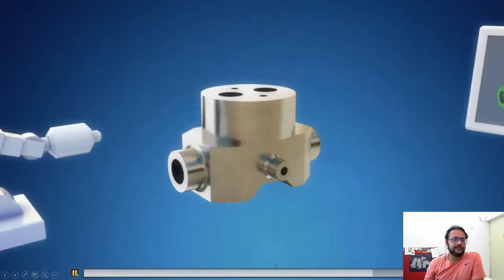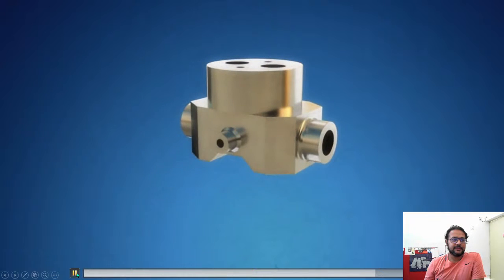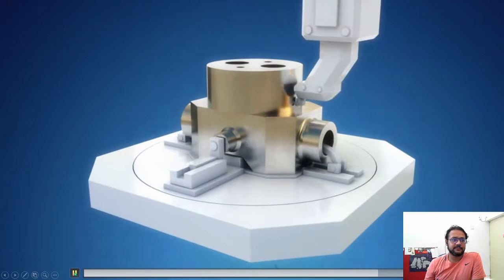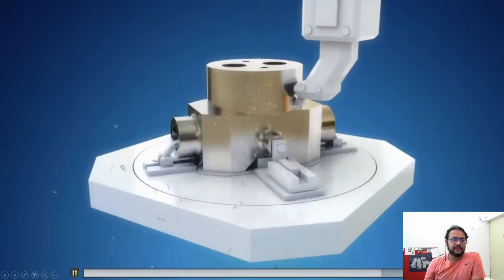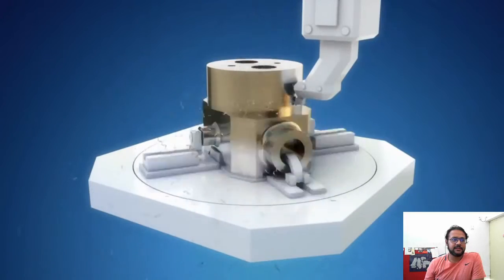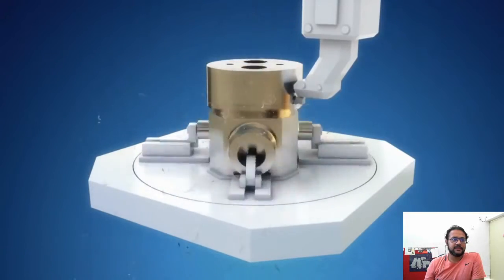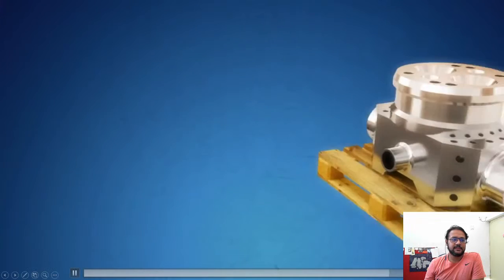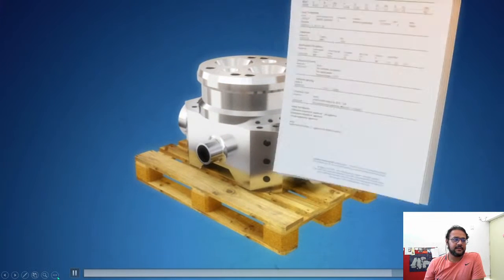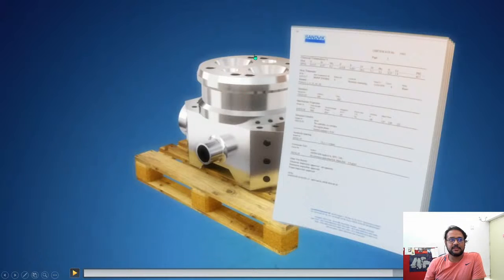Dimensional requirements. The uncovered product needs no or only minor machining, since the hot isostatic pressing process results in a near net shape component. The product is ready for delivery, accompanied by certificates. So as you can see, from that near net shape, this kind of final part is delivered, where you would have these machined holes and all these kind of chambers and all that.